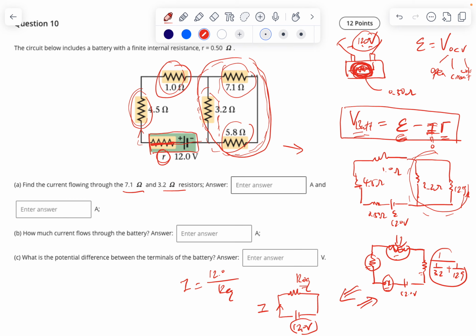Then you go back to here. So those four connect together in series, right? So the current is the same. So the current through this one, everything is the same, right? So you know the current. And then once you know the current, you can figure out the voltage on everybody. Especially you can figure out what's the voltage here. And once you figure out the voltage here, the voltage here is current times this resistance, this whole thing, right?